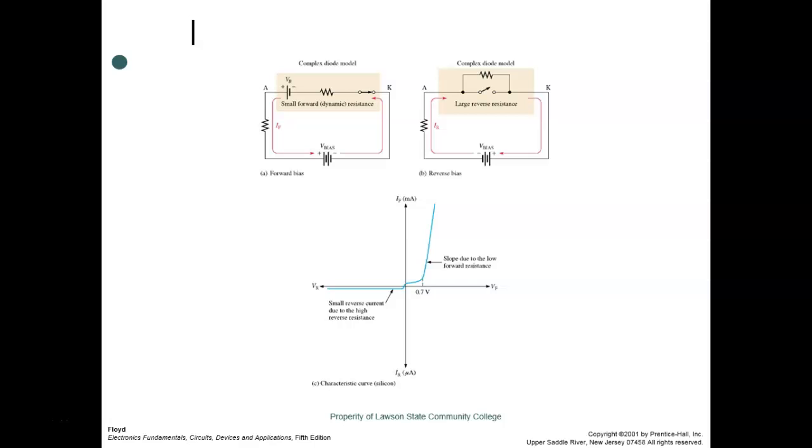But for practical purposes, 700 millivolts works out real well, because back in DC, what did you have to do to all your resistors? You measured them, and when you did your calculations, you didn't use the color coded value, you used the measured value, because you were trying to prove Ohm's law, that V is equal to I times R.